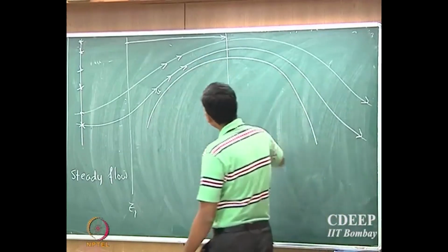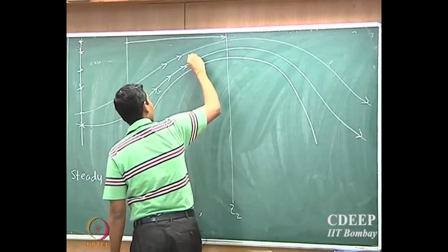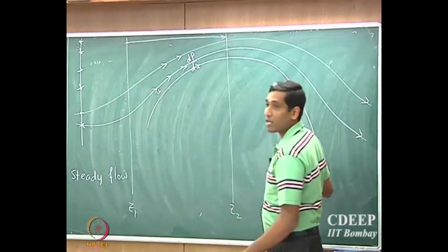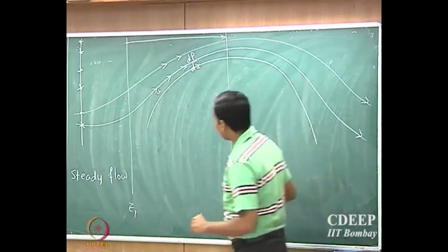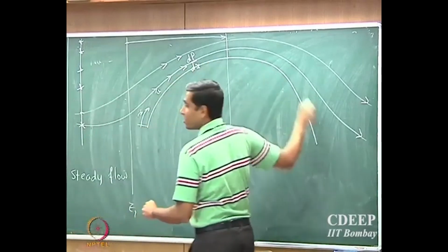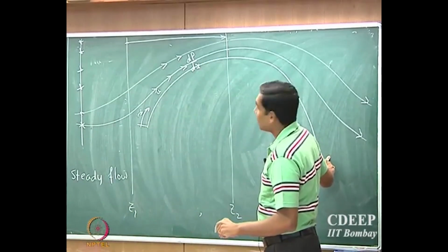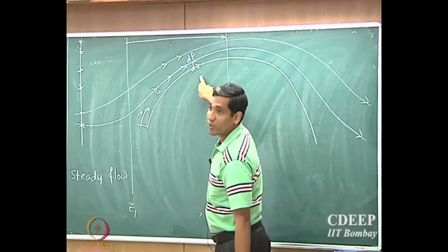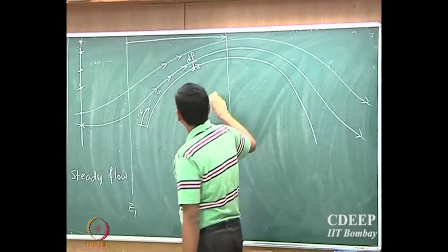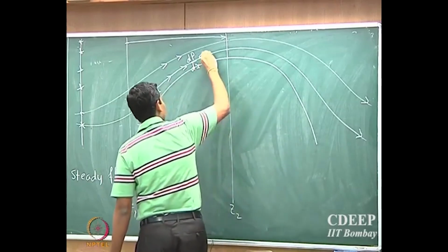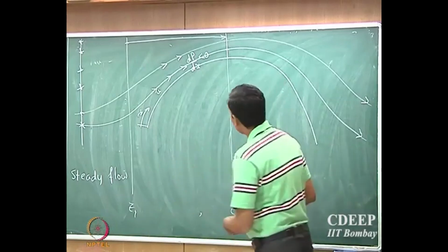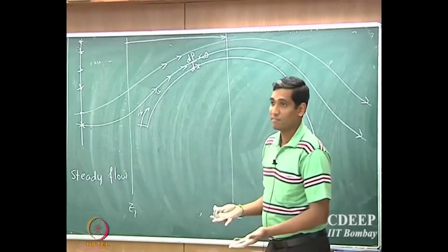So therefore, if you look at the pressure gradient, note that here the x coordinate is the curvilinear coordinate, not the linear coordinate. So the x direction is the location along the curved surface, and so dP/dx along the curved surface has to be less than 0 in order for the fluid to accelerate. Now that's not true everywhere.